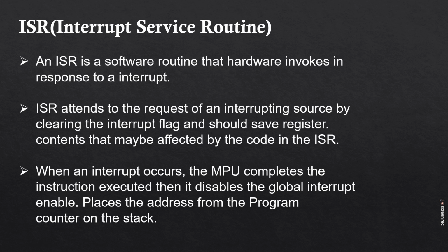Then we're gonna discuss interrupt service routine. So basically an ISR is a software routine that hardware invokes in response to an interrupt. ISR attends to the request of an interrupting source by clearing the interrupt flag and should save registers that may be affected by the code in the ISR.